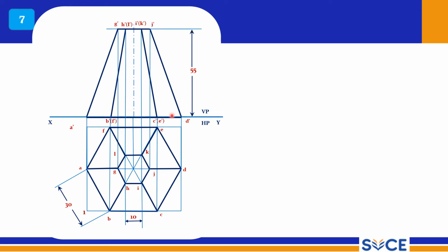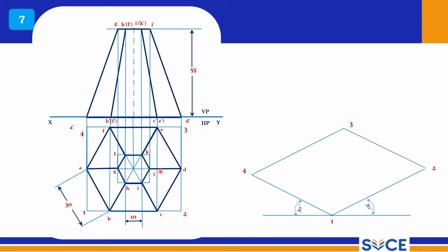So this is the front view on top view. Now enclose this within a rectangle, and one more rectangle for this smaller hexagon, right? Once you draw this front view on top view, the isometric view is very simple to project. So this is point A, B, C, D, E, up to F, right? So this is the center point.